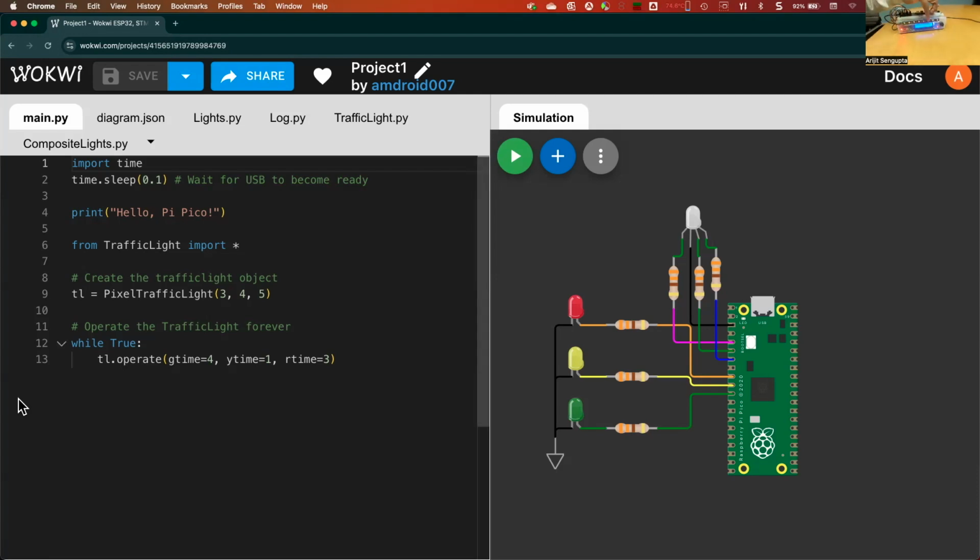these light strips. And you guys probably have seen some of these. If you have Christmas lighting or accent lighting, you can easily go on Amazon and buy light strips that have 10, 15, 20, 100, 200 lights connected together. What is really cool about it is that all you need is one I/O pin to control all of these LEDs individually. And the magic behind it is that each LED actually also has a control chip in it.